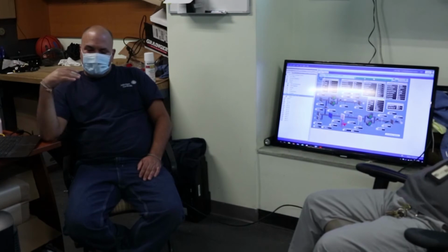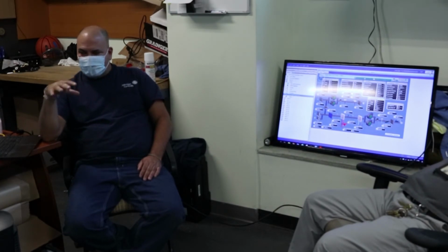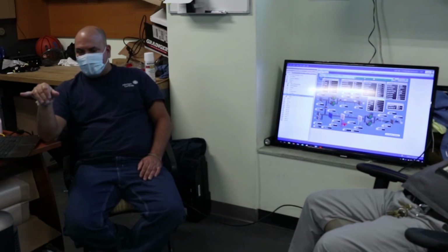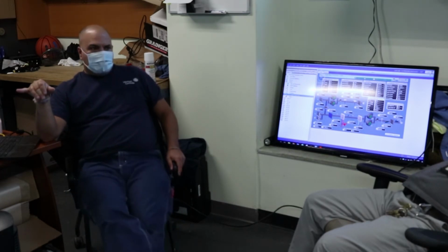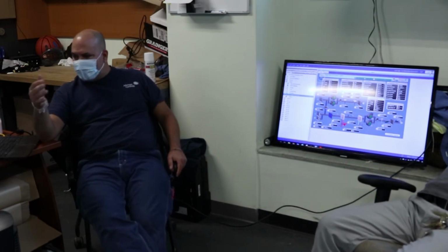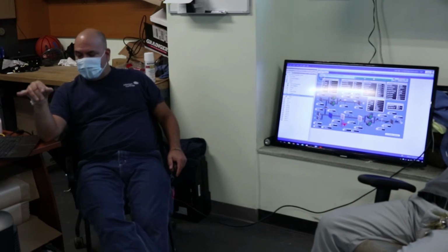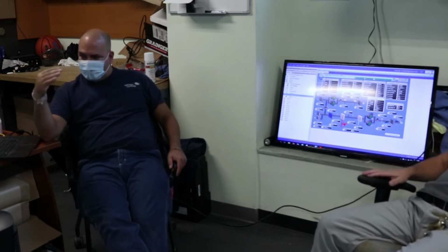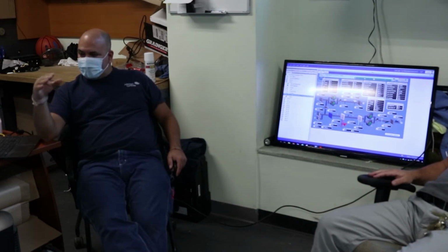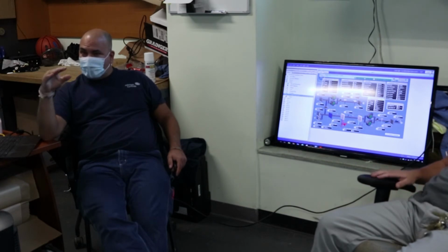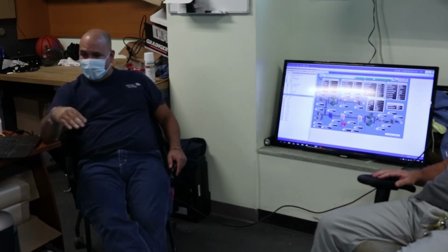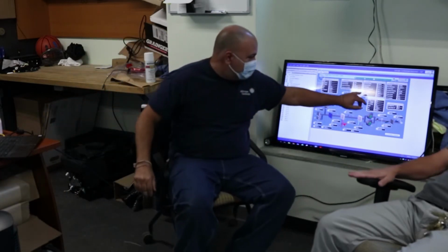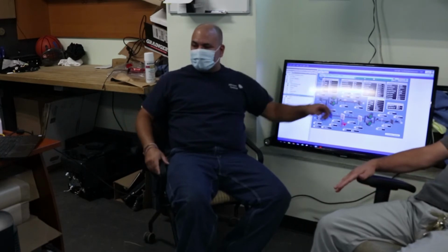It takes the damper position of all the VAVs associated with that area. It's probably 40 VAVs per area. So you've got a total of somewhere around 500 VAVs for the 8 air handlers. It takes the average of the damper position and resets the discharge air temperature half a degree per hour based on that schedule. That's where you'll see the effective DAT. It tells you what it's actually looking for.